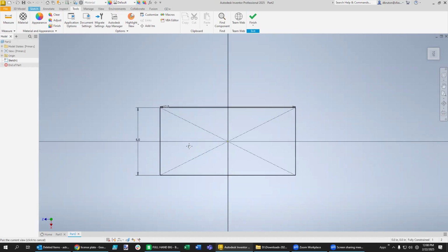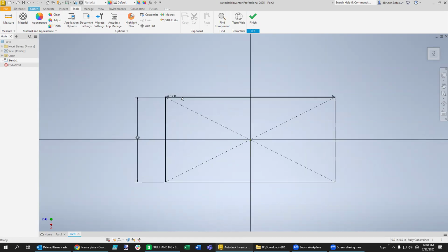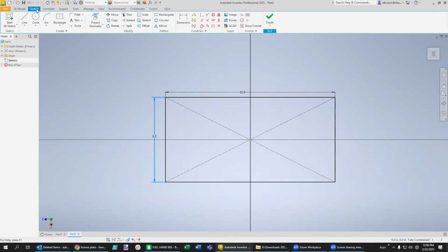Okay. Now, if you look up the standard radius of curvature on the edges, you'll find out that they're about 1 inch. So we will do that. We're going to do that with a sketch fillet. Here it is. And I've learned that it's better to come up here and type it in first before you go select the two areas to curve. It looks a bit more than you normally get for that, but that's what I was finding.